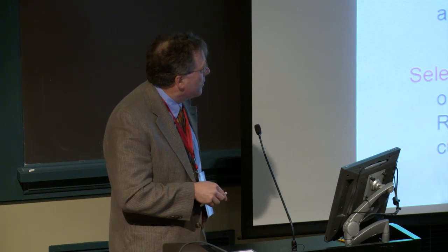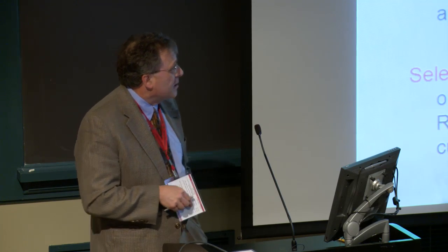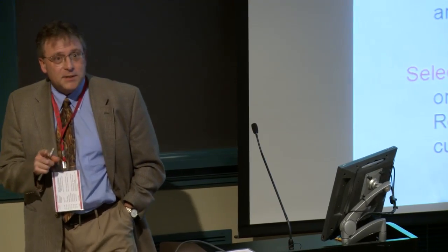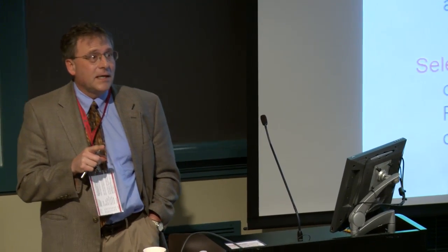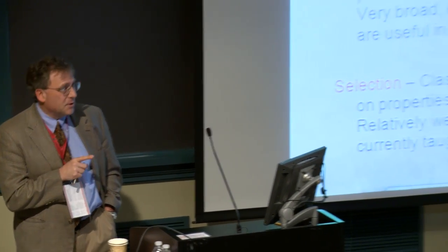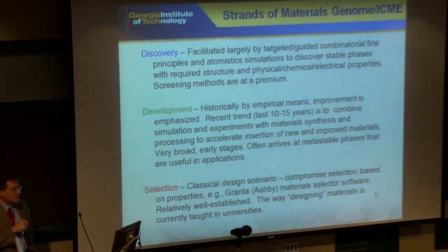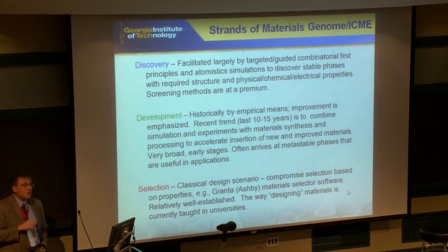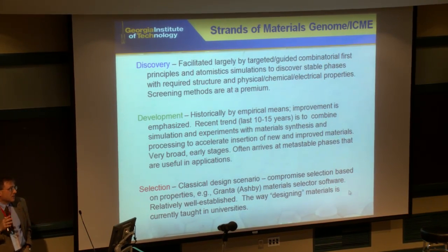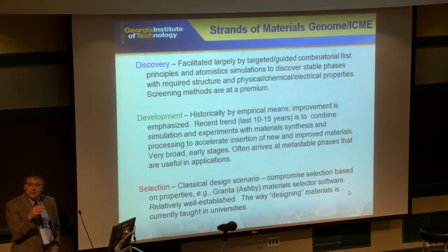And I just point out here that in development, oftentimes it's metastable phases that we rely on for in-service performance characteristics. You know, that if you take them up another 50 degrees centigrade, you'll get coarsening and you'll destroy the structure. But you go up to that ragged edge and you understand the kinetics of the coarsening behavior, segregation, et cetera, that limits that. And especially in the aircraft gas turbine engine business, this is a big consideration.